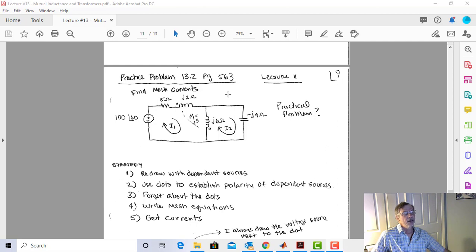So if we know the mutual coupling or the mutual impedance, then we know what's going to happen in this circuit. Now I want you to keep that in the back of your head because that's not entirely practical yet. It's going to get practical in an example we're going to do later down the line, where we are going to figure out what the mutual coupling is based on the circuit behavior. And that is absolutely practical. Because suppose an engineer designs a circuit and says, I expected to get this over here, but they don't. What we can do is look at the geometry and say, let's hypothesize mutual coupling and wiggle the value of mutual inductance around until we get the result that the engineer sees. Now we know how much mutual coupling there is. So I just turn it around a little bit, but you're going to see that in a problem down the line, and it's a very, very practical problem.